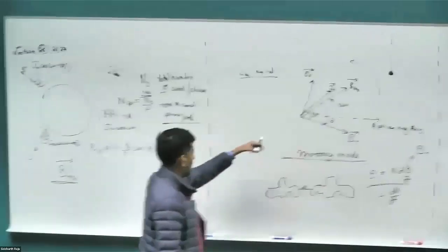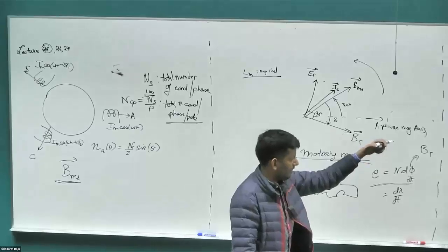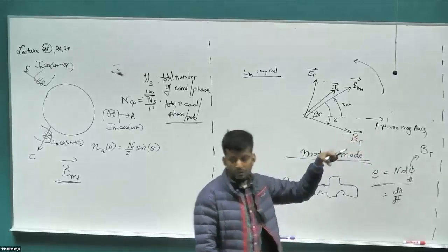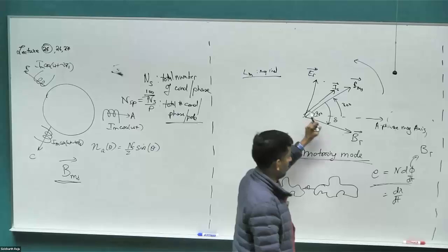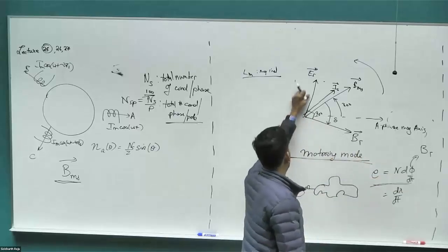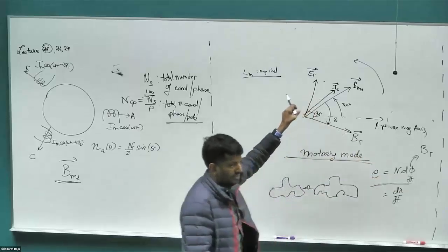So wherever our rotor magnetic field is going to be, in turn the rotor flux direction is going to be pointed that way, flux linkage is going to be pointed that way. You take the differentiation of it, you get a j term added onto it, which is basically rotating this vector by an angle of 90 degrees. Right?